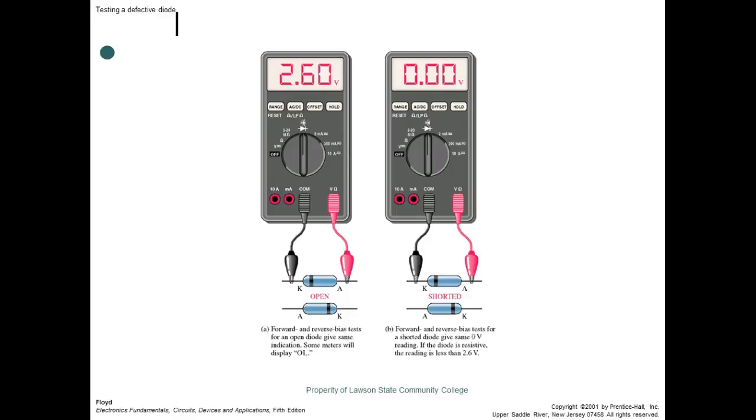So an LED is a good example. Light emitting diodes are great, but they have real low breakover voltage. So if you put an LED into a 120 volt circuit, it's going to pop it every time, no matter what resistance. But you could take a regular LED and put it in series with a diode that's got 200 volt breakover, and the LED would work right. So yeah, we use them in series all the time.